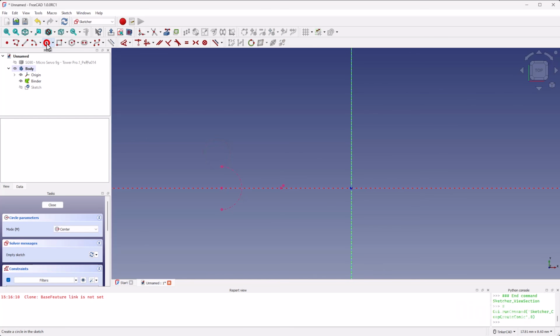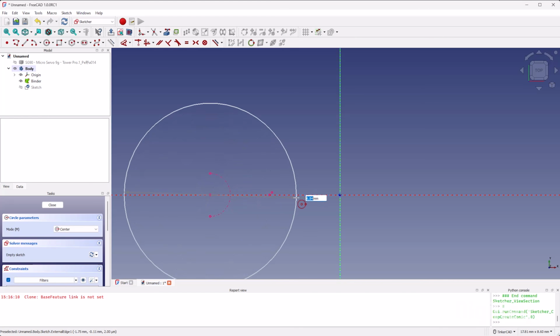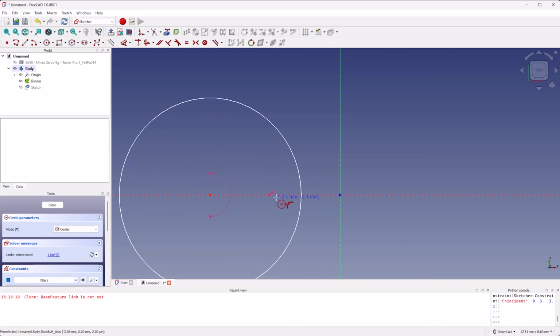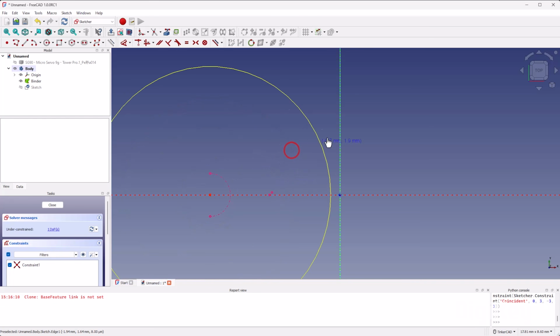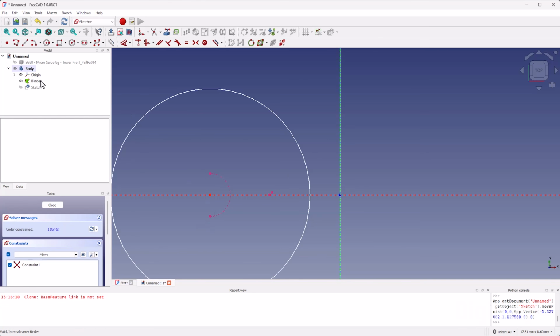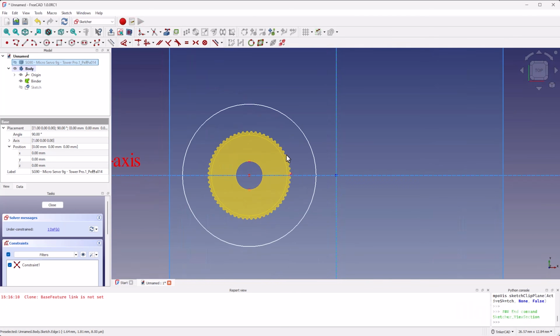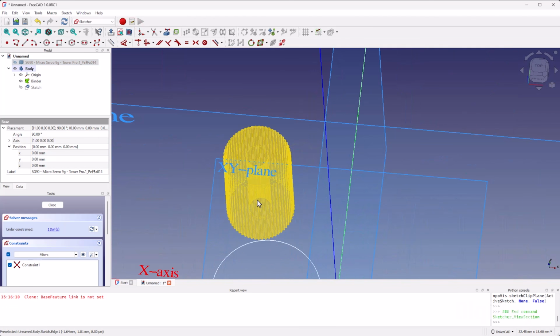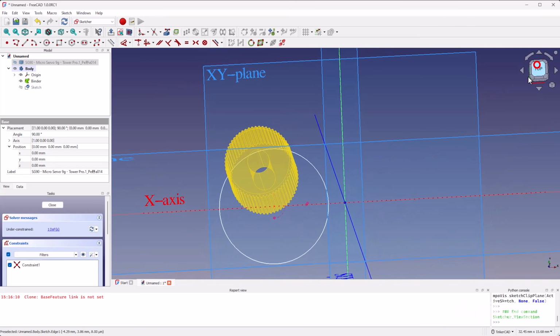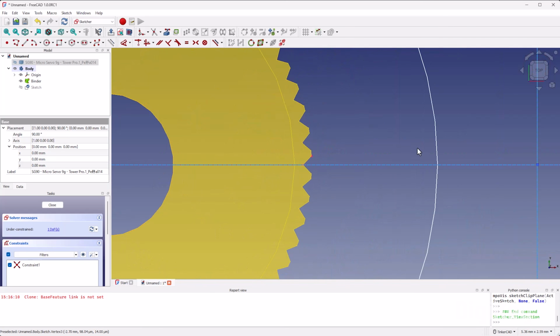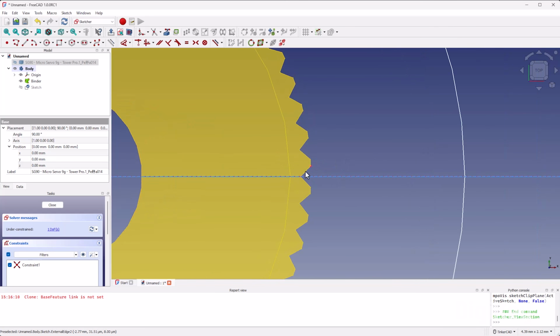First thing I'm going to do is click to create a circle. I want to create it out from this hole here. I'm going to make it bigger than where those gear teeth are. Right click, notice that the circle is based around that center point of that gear. So let's view section. So you can see we're going to create a pad that's going to cover that shaft for us. And we want to make it 2 millimeters bigger than this point. Now, I can't quite make it horizontal here. That's not quite how that works.